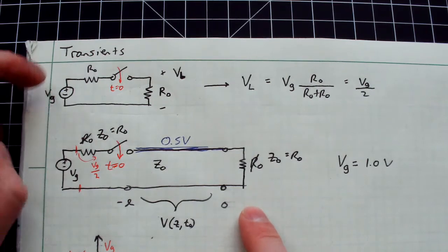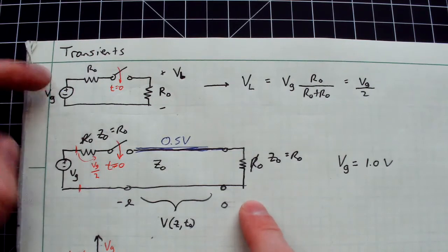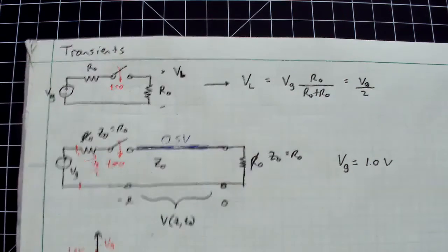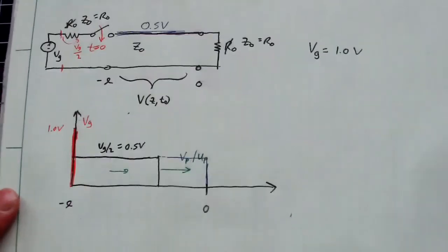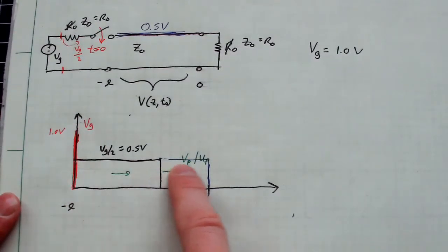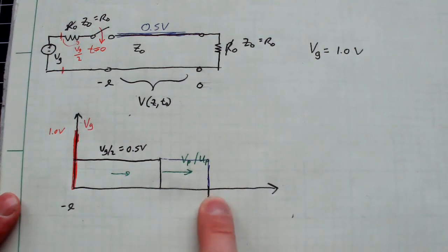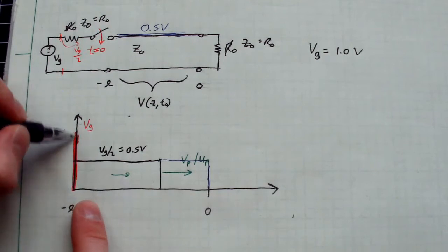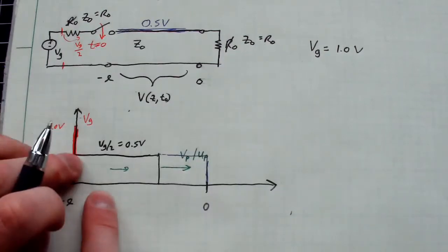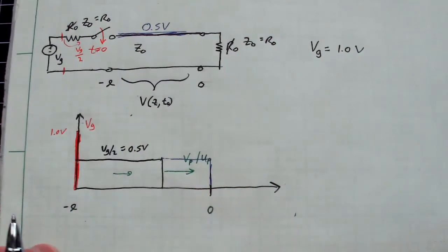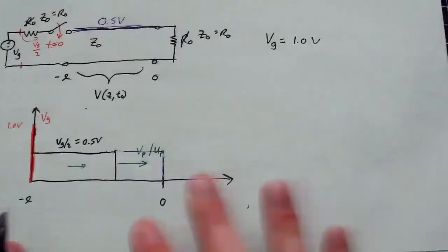So that's another kind of approximation inherent to circuit theory, that you can think of it as a steady state solution to this kind of effect. Okay, so after infinite time has gone by, this half a volt goes across the entire line and then just stops at the load. But this is an important notion, that there's this voltage division here. Here at my generator, I have 1 volt, and over here inside the line, it will be a half a volt. So this makes an interesting, quick little sidebar.